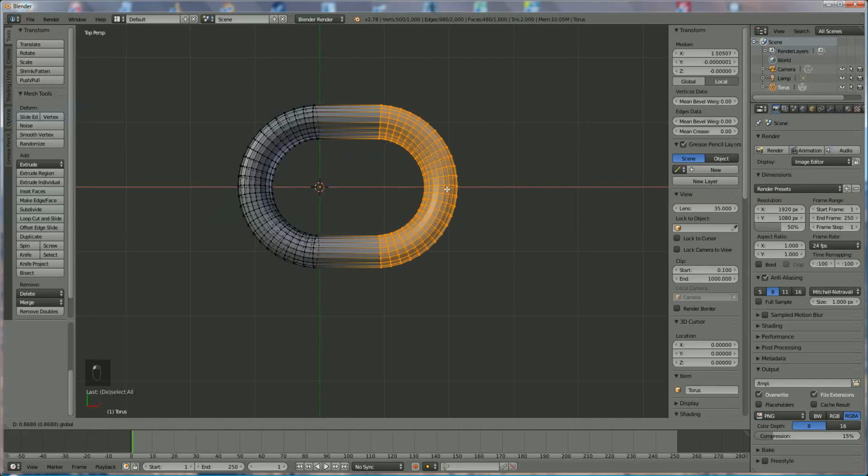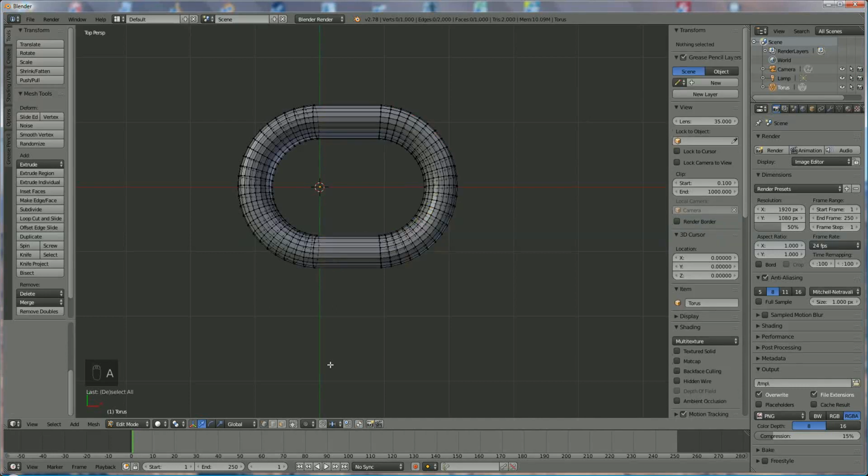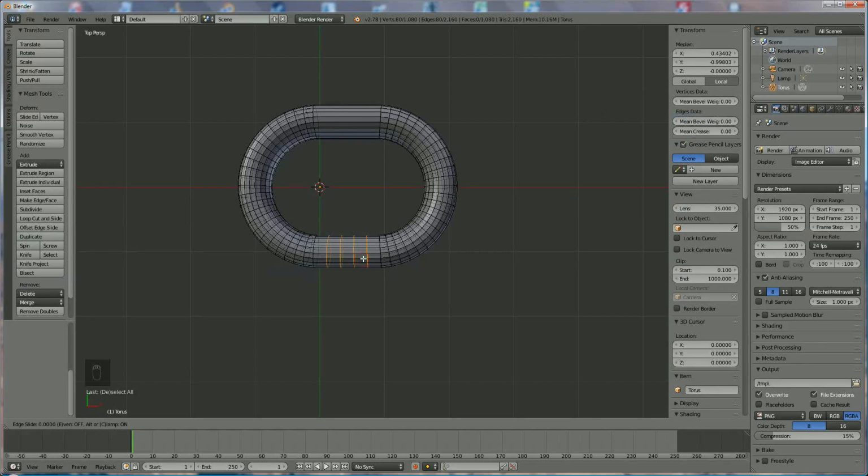Now move it aside like this until you have your chain. Let loose. Now press A again to deselect. Now Control R and select the top of it or the bottom, it's not important. Roll with your middle mouse key until you have 4 rings in purple. Left mouse click. And now press S X because we want to shrink them in X direction, something like this.